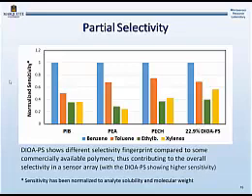So you can see selectivity is relatively limited, so that's why we use the response time constant in addition to the frequency change. But you can already see that the polymer plasticizer blend after normalization gives us higher sensitivity to ethyl benzene and xylene compared to all the commercially available coatings. So it does make some contribution to the overall selectivity of a sensor array.